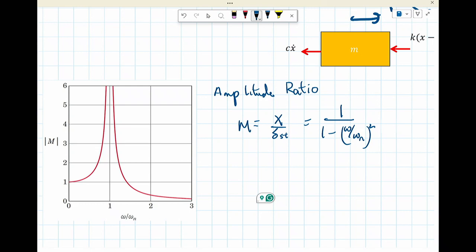And if I do that and I look at the ratio omega over omega n, I go from a magnification of 1 on the left-hand side as I approach the natural frequency of the system. I go towards a discontinuity, and then as I go away, I also have a departure from a discontinuous non-reasonable solution to one that does work.